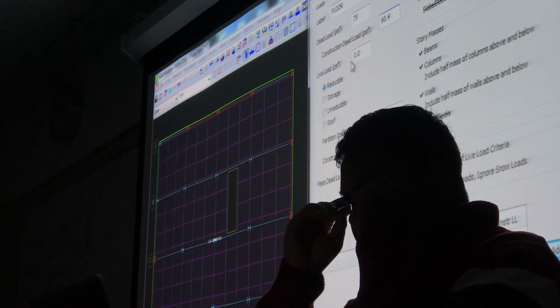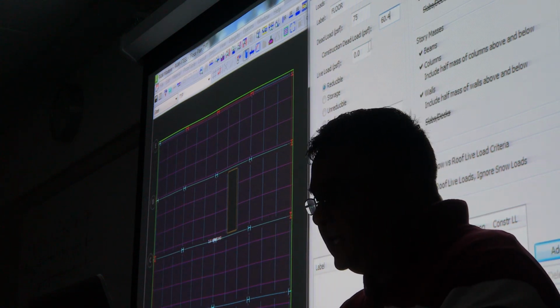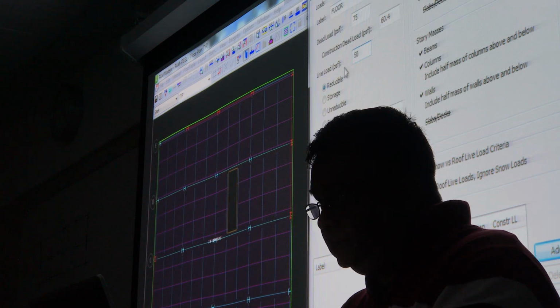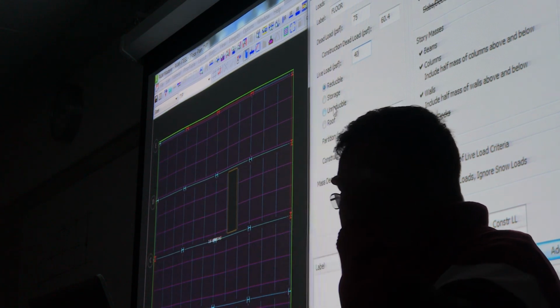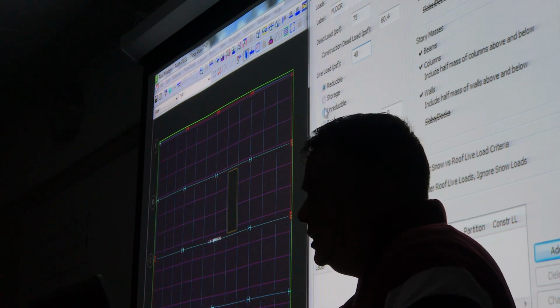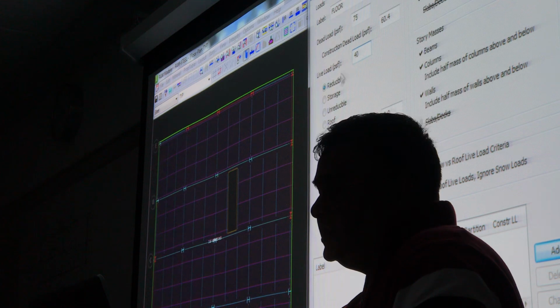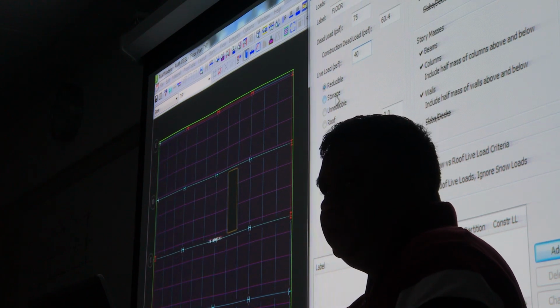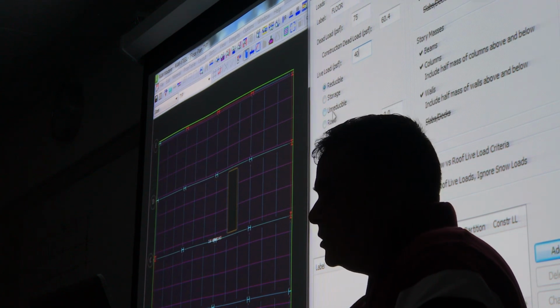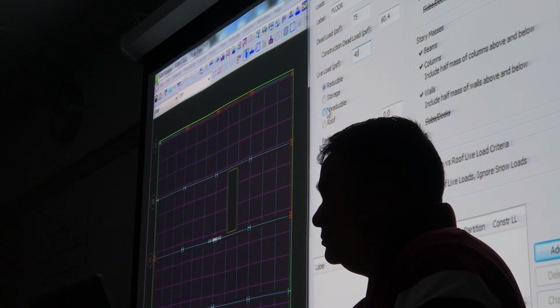Okay. So I'm going to use that live load 50 PSF or 40 PSF. 40 PSF live load, reducible, yes. If it is at the roof level, you can click on that. If it is more than 100 PSF, so it's a storage, don't use that. Use storage, that means it cannot be reduced. If you do not know, but it's more than 100 PSF, it's unreducible. Okay.